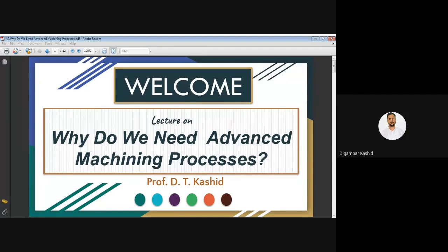As we know, our manufacturing processes can be divided into two types. One is the primary manufacturing process and second is the secondary manufacturing process. Primary manufacturing process means what? These processes provide the basic shape and size to your workpiece or material as per your requirement, or as per the drawing or the designer's requirement. Which are those primary manufacturing processes? In that category, you can take example of casting, forming, then powder metallurgy. Processes like that you can include under the primary manufacturing process.